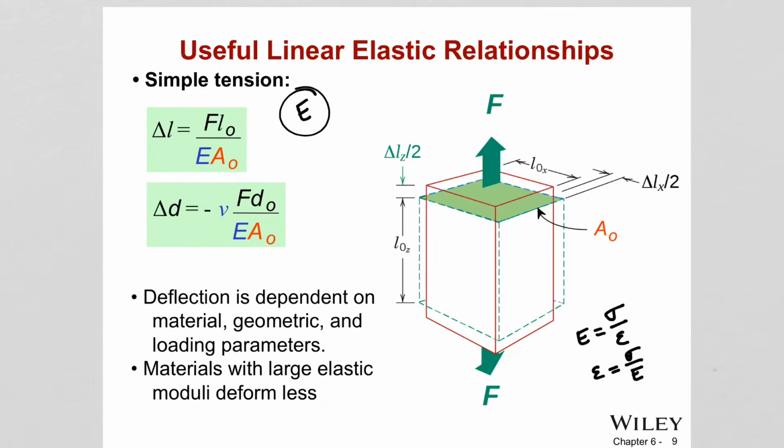Okay. So when they collect the data from the tension test, they measure the force at the device, and from the force they divide by the cross-sectional area, and the test equipment gives us this curve. We call this the stress-strain curve, and on the y-axis we have stress, on the x-axis we have strain.